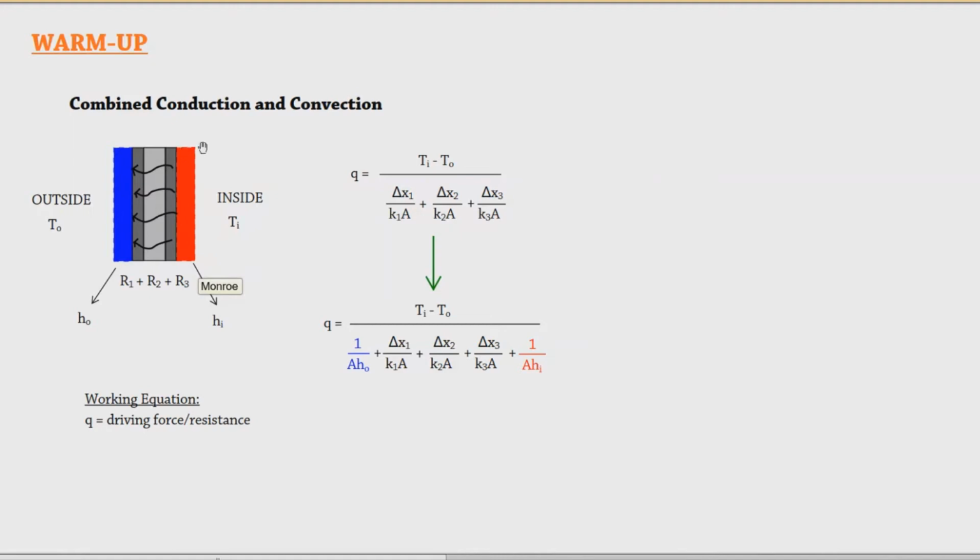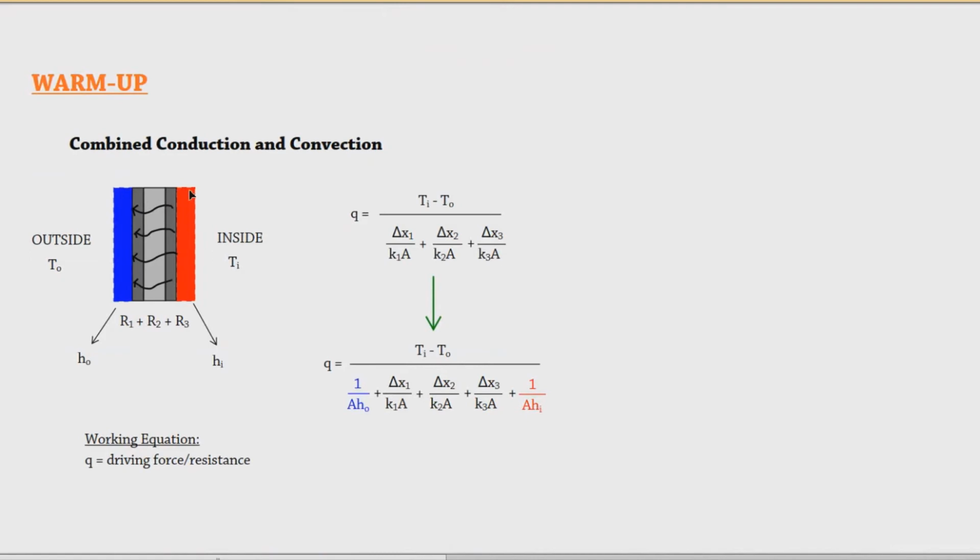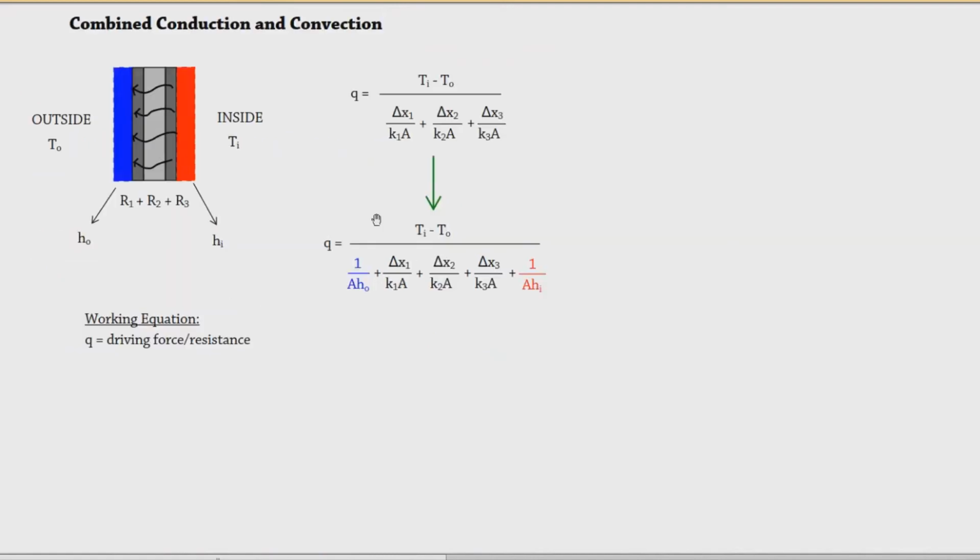So instead of representing that in terms of thickness, we refer to it using the heat transfer coefficient, H. If this is another resistance, we'll be adding that to our equation, and the equation becomes something like this. Since we don't have this delta X, because they are not solid, the fluid will be represented by 1 over HO, where HO is the outside heat transfer coefficient. And it makes sense for the inside, which is HI, the heat transfer coefficient on the inside.